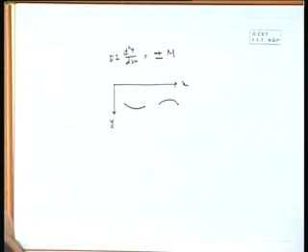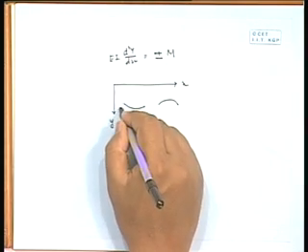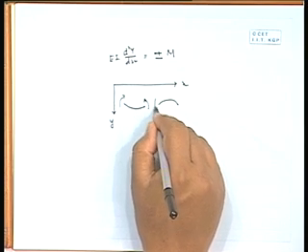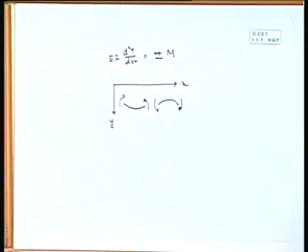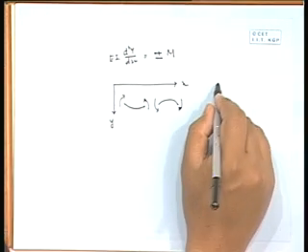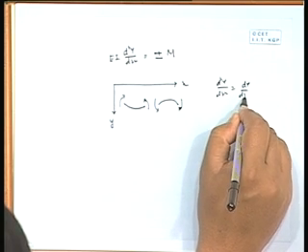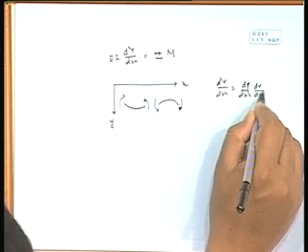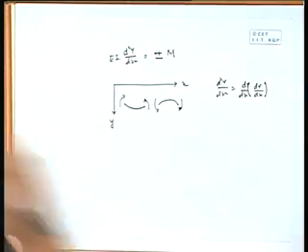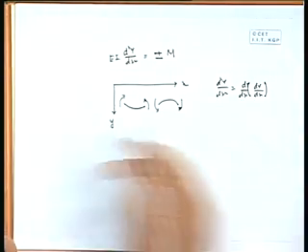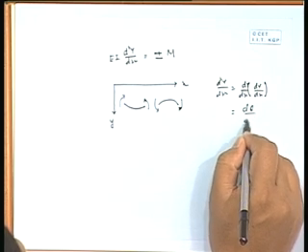So, earlier we were trying to define sagging and hogging type. Now, here there will be a type of moment, and here there will be a type of moment. Now, x, y. d2y by dx square is what? d2y by dx square we can say is dy by dx of dy by dx, and dy by dx is what? It is basically theta. So, we can write it is d theta by dx.